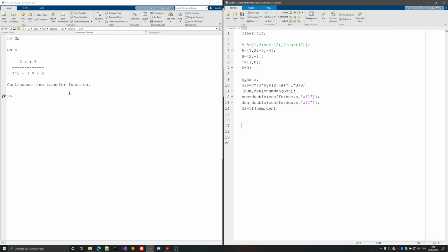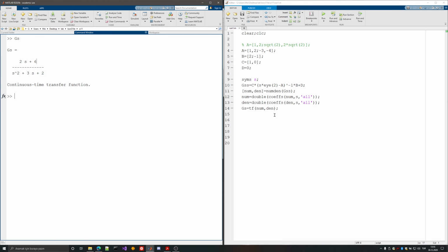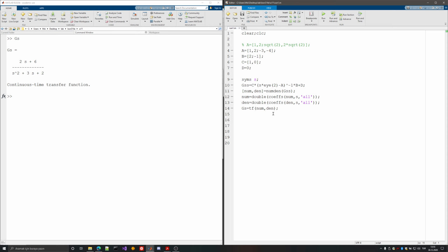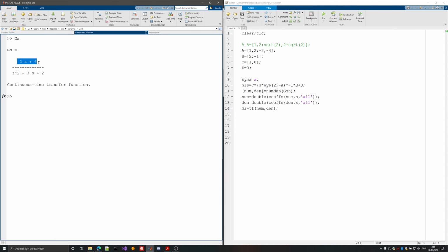Well, basically, the first step would be to get rid of the numerator, and keep in mind that this is only my method. You can do it differently, since there are an infinite number of state space realizations. But I like to get rid of the numerator here, which means that I place a 1 here, and define this as the relation between the input and the states.